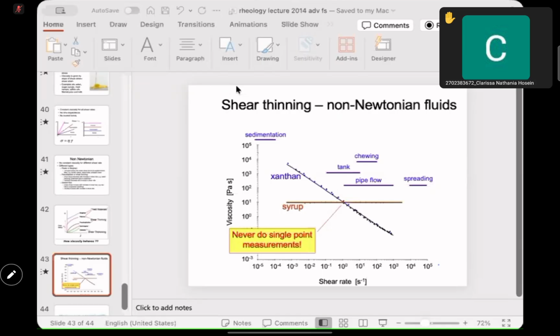The first is about a debatable question. Does true yield stress actually exist, or is it just a measurement limitation? Some rheologists argue that every material will flow if you wait long enough or apply even the tiniest force. Others mention that for materials like ketchup, the internal network of tomato solids creates a genuine physical barrier that prevents any movement below a specific threshold. Does true yield stress actually exist, or is it just a measurement limitation? That is my first question.